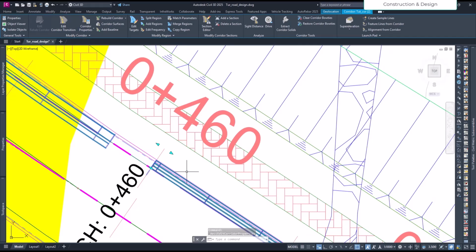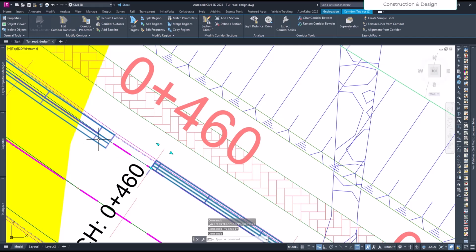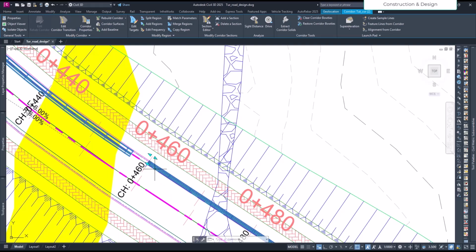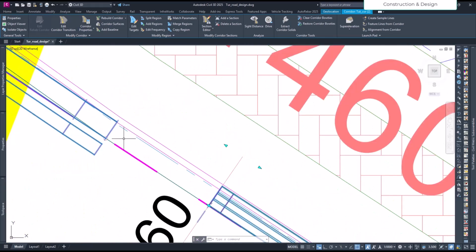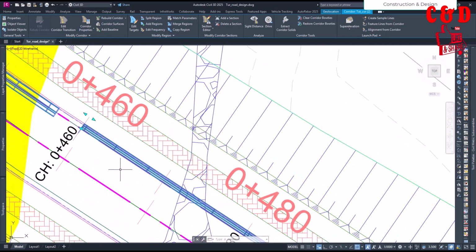Don't worry if you see these gaps. This is just about the frequency. You increase the frequency and you can fill it. Also, when you have a beam, there is a specific detail that you have to provide for Jersey barriers. It will go into a concrete and end here, and then the Jersey barrier will start. That's about the detail. Details are different based on your location and your specification.